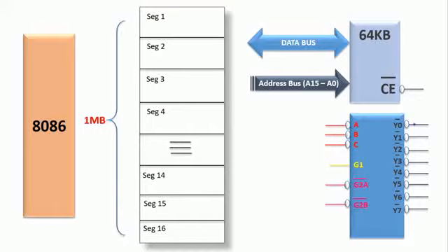When you do this, you are mapping this particular memory device into one of the segments provided by the microprocessor. This is the space provided by the microprocessor, and whatever division we have is a virtual division. For your sake, I divided this into a virtual format.